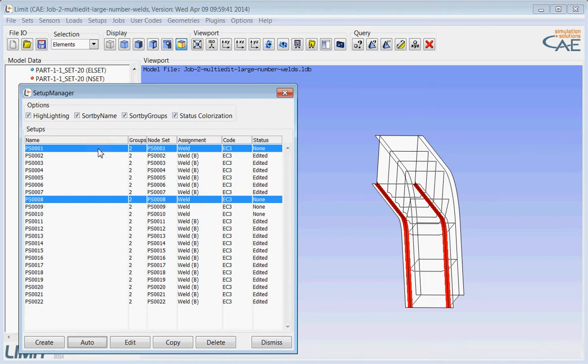They again could be double-sided welded, so we could have a welding sequence of first welding the webs to the flange, then introducing the ribs, and at the end closing it with the upper flange. So the longitudinal welds on the lower side could be welded from both sides. That's what we're going to do.